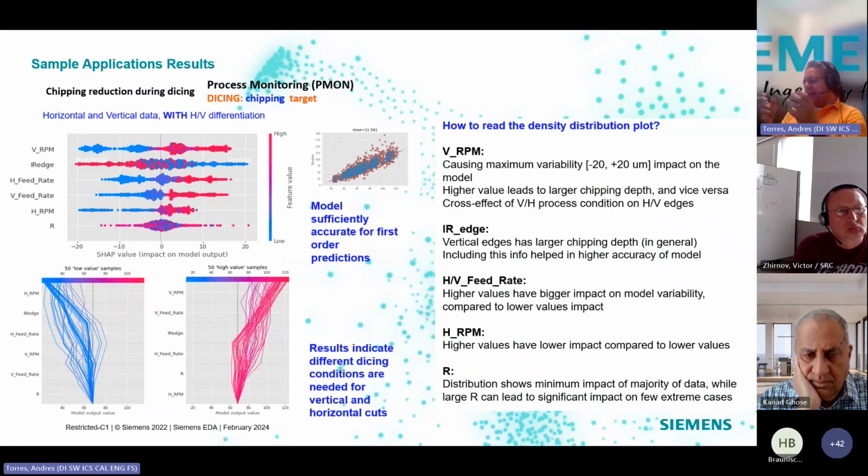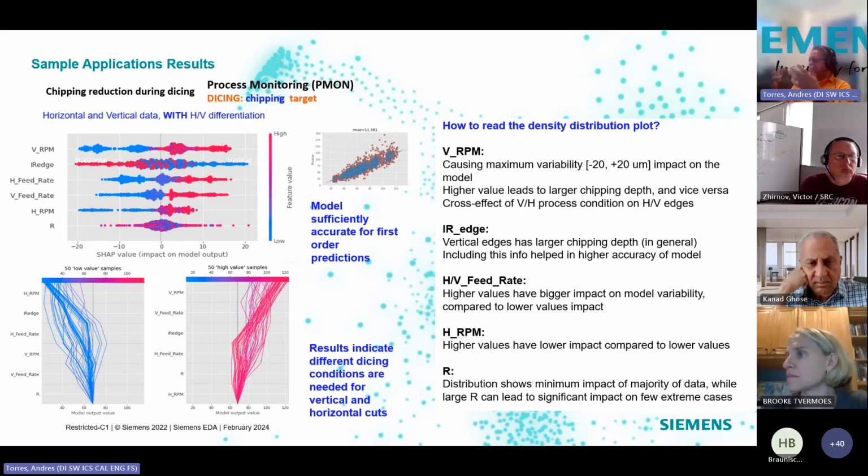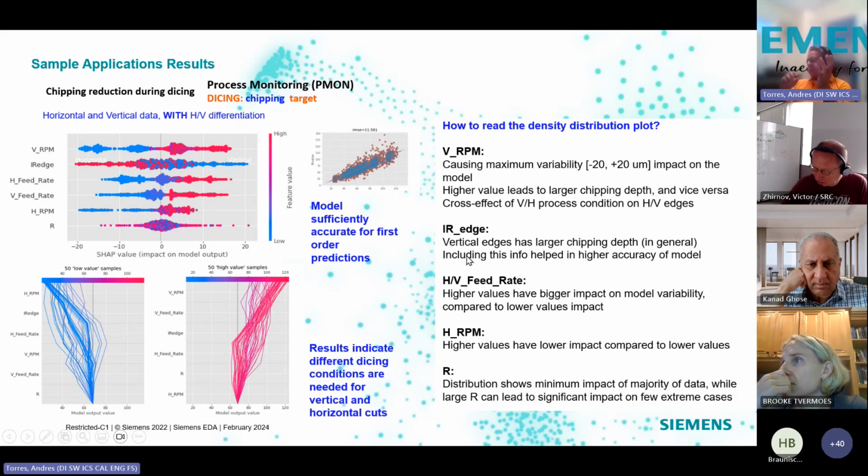Now, since this is intended also for packaging, what I wanted to highlight is that building a digital twin is not only about having the tools, but having the philosophy of how you dissect the problem and what numerical techniques you're going to be using. In this case, all of the technology that was shown before was developed for semiconductor manufacturing. That same technology was used for a dicing problem. Dicing has really nothing to do with etch, lithography, or deposition. It's literally a blade making cuts on the wafer.